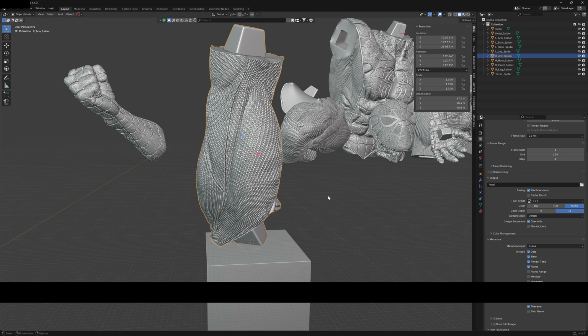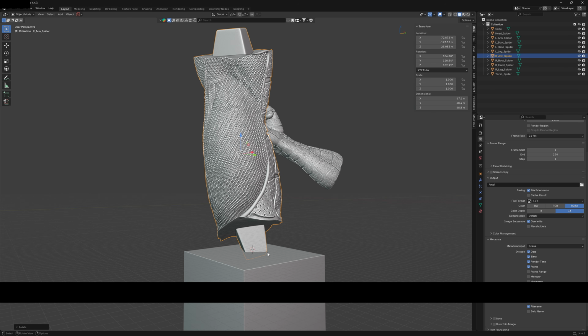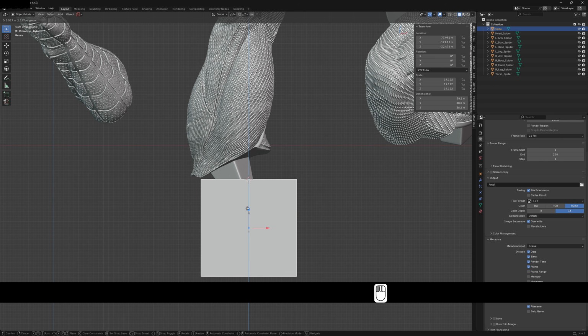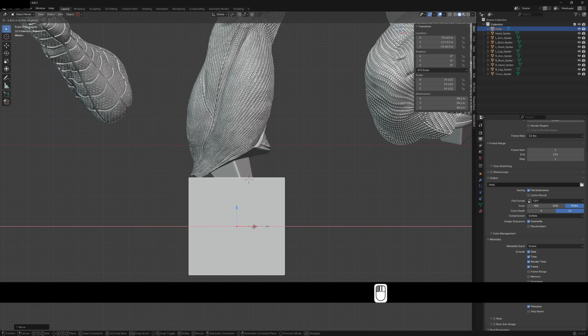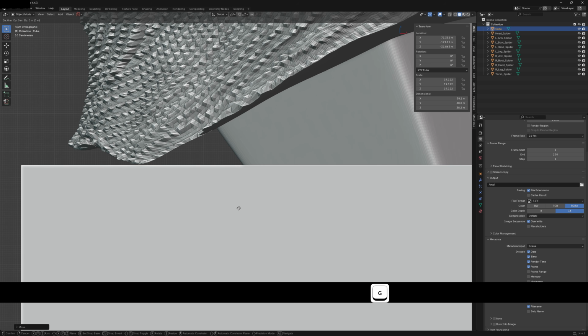This isn't leaning too much. I'm going to rotate it to the right a little bit just to get this corner covered off. And then zoom in a little bit. If you can't see the movement widget here, remember, you can press G and Z. So I wanted to move it. If you just move your mouse up and down, it's quite sensitive. But if you hold down Shift, it'll scale the movement down. So I reckon you could just get that little corner to touch as well.